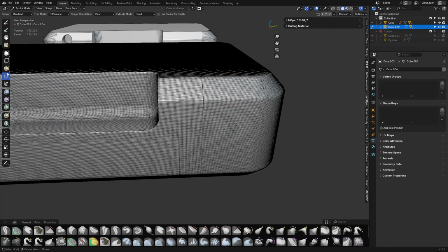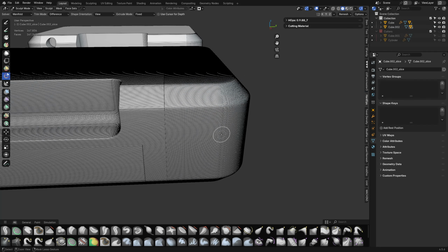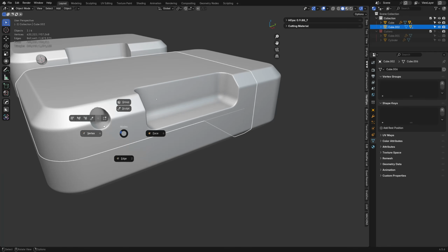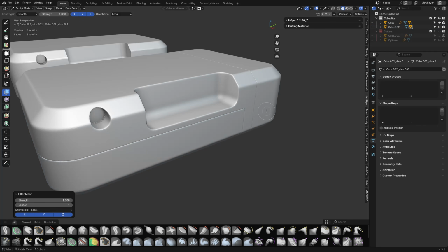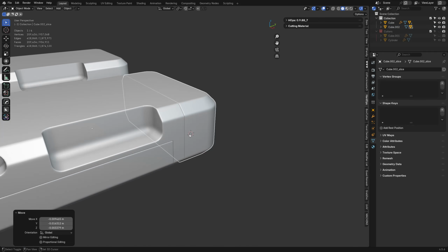This is also why you might wait to do remesh or smoothing later, because you still got to remesh a number of things possibly. But anyways, with all this done, these pieces we can mesh filter, smooth, and we can smooth them down a little bit. Alt Q to this one, smooth it down. Alt Q, smooth it down. And we can continue working on this, right?